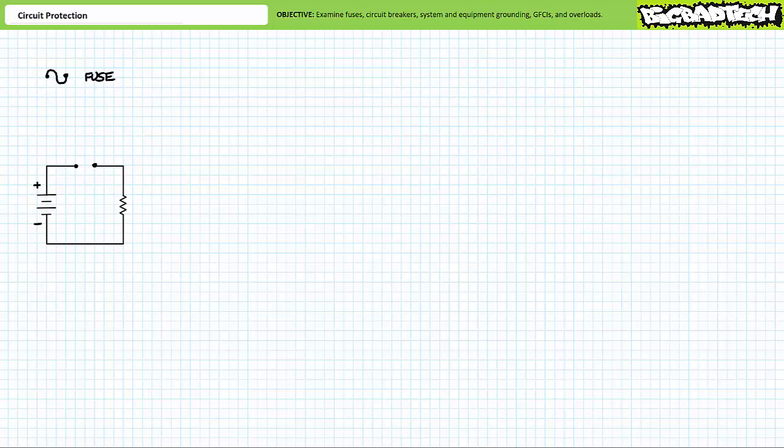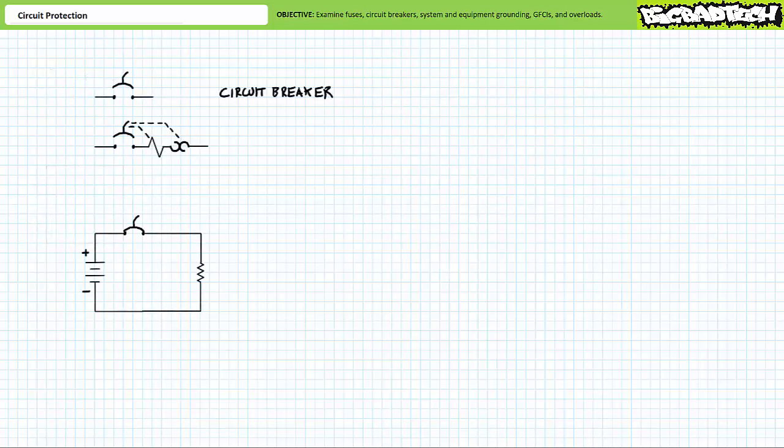There's not a lot more to say about fuses except this. Fuses are non-reusable devices designed to protect the system from high current. They do not protect operators from leakage current. I'll return to this point in a moment. Let's now briefly discuss the next circuit protection device, the circuit breaker.